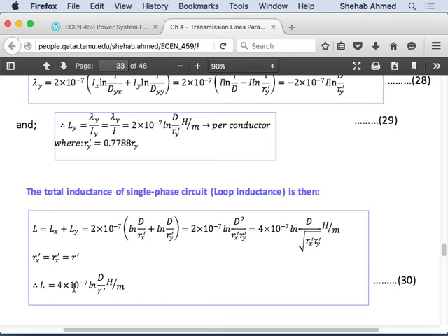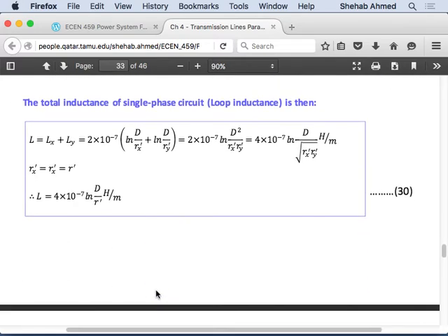This is another big advantage of three-phase systems because, again, if you're consuming the reactive power of the generator to supply your inductances, right? These inductances are consuming reactive power. Then your generator's capacity is affected, because generator capacity is in apparent power. If you need to supply reactive power, it eats away from your ability to provide real power, right? So this was one example.